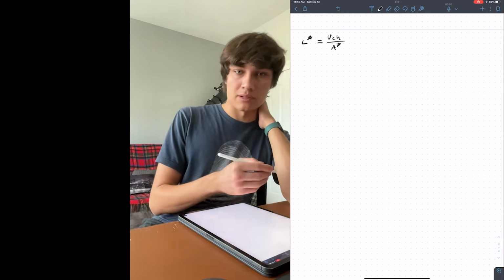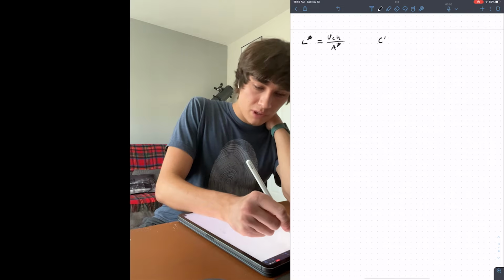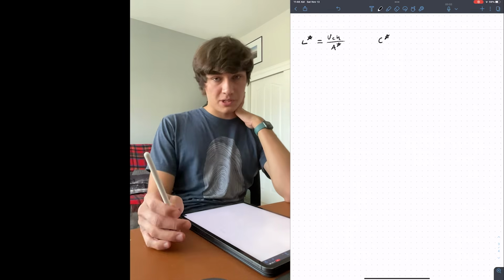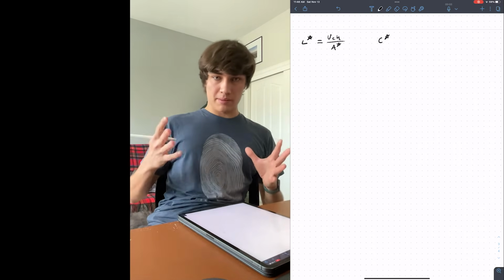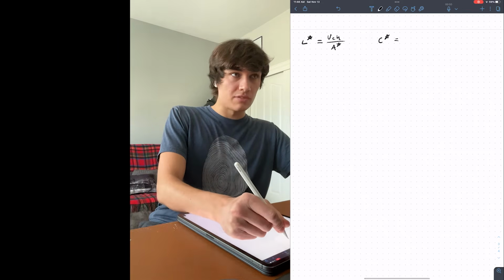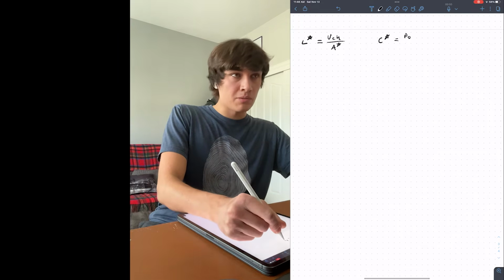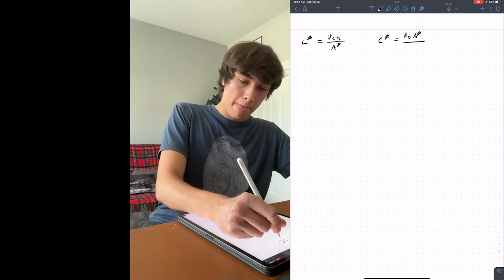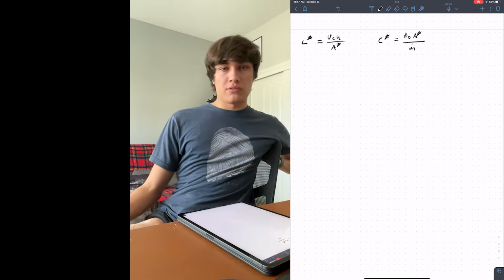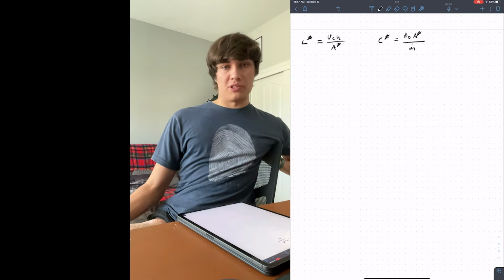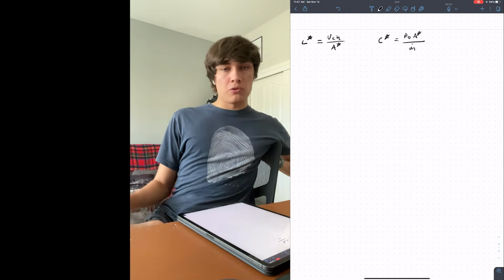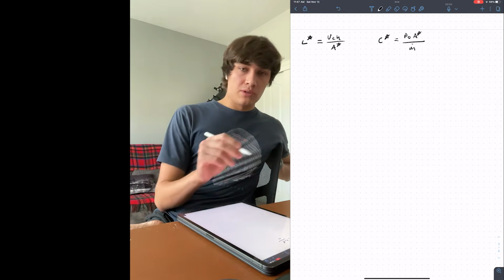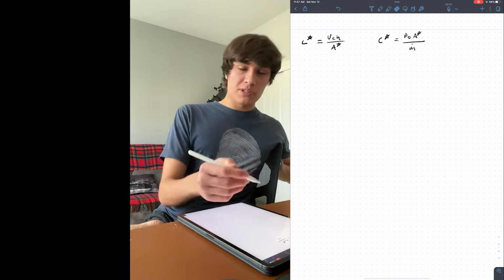Another important performance characteristic of a rocket engine is called C star, which is characteristic velocity. Now remember when I said that the exhaust velocity is the primary performance metric, and it is for the idealized chemistry. The characteristic velocity of a rocket engine is defined as the stagnation pressure times the area star divided by mass flow rate. This serves as a proxy for combustion efficiency and injector performance. So your injector will not fully mix the propellants, and your combustion will not be fully equilibrium. So when you have a test fire and you measure the C star, all of these parameters are easily measurable.